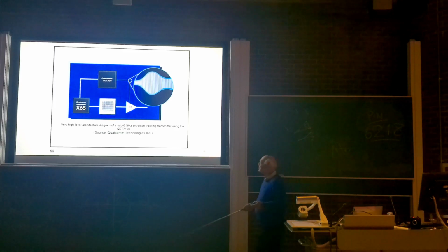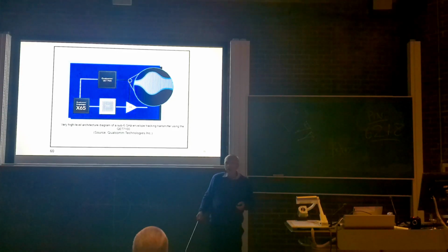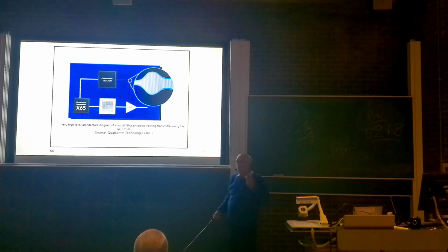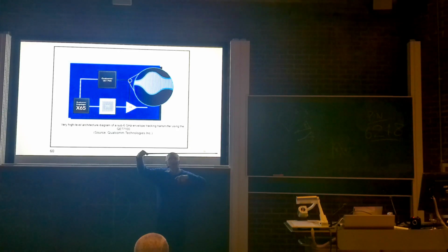This is a different aspect. It's much easier, when you've got this 16 QAM signal, to actually get it to the output in two ways. You clip it and make it a constant amplitude signal, which retains all the frequency and phase information, but it does not retain the amplitude information.